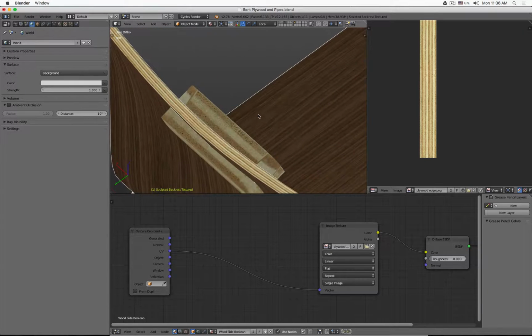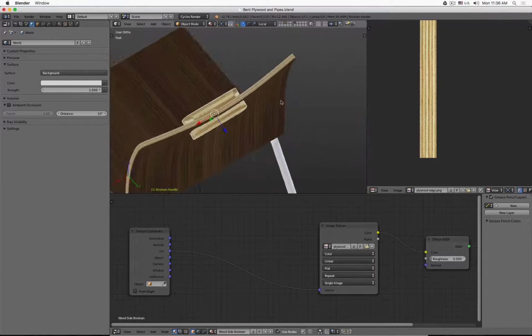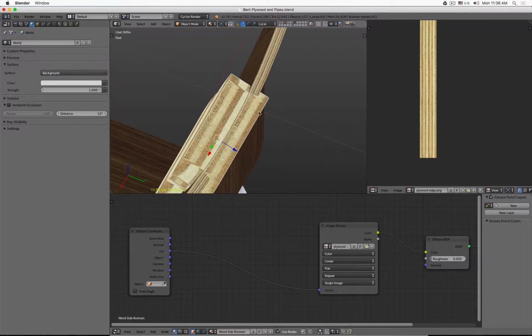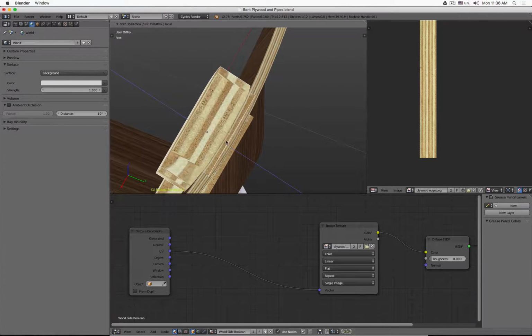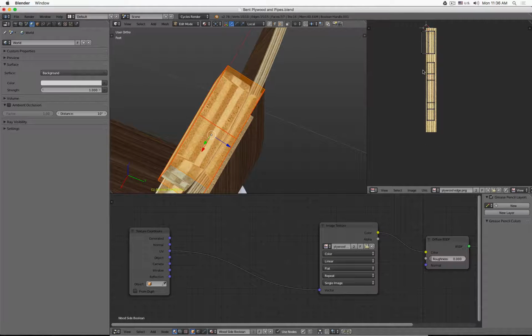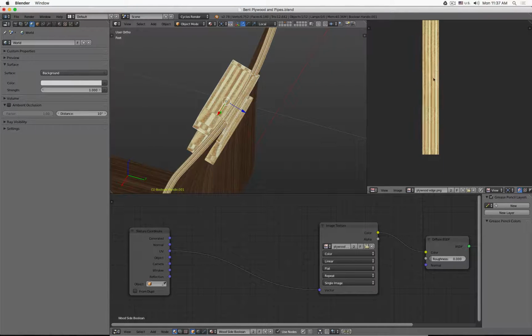So the problem is, as you can see, the texture here and on the Boolean object don't really match. So I will Alt D, make a copy, escape, and then I move the copy up so I can see it next to the other object there. Because it's a clone, when I go into edit mode and I select all those faces, S and X, as you can see, I will adjust the UV unwrapping for both objects.